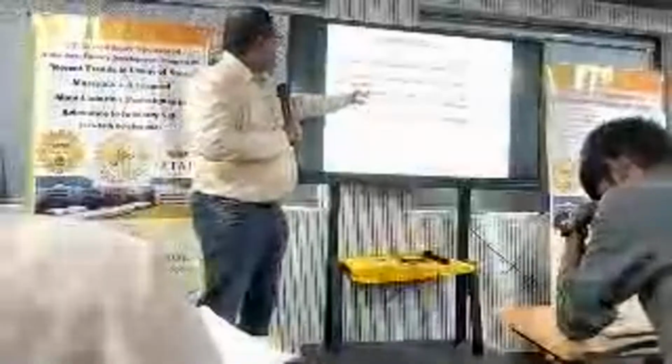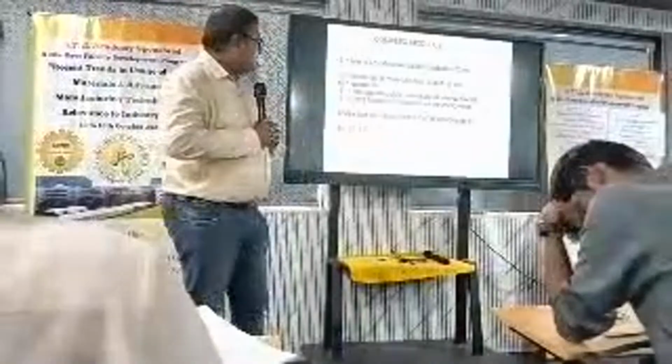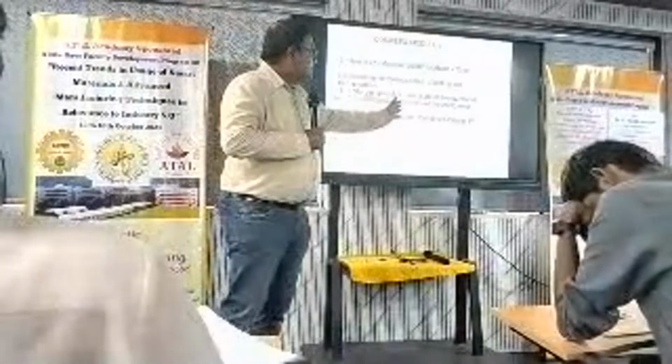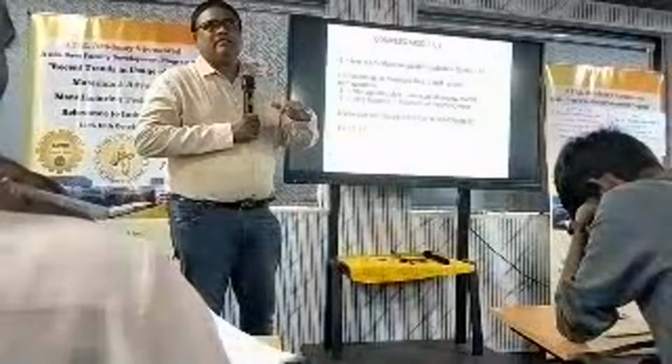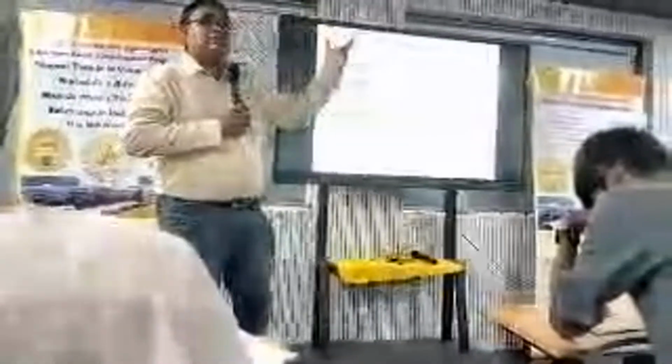E star is a complex number which mainly depends upon the storage modulus and the loss modulus. Loss modulus is the measure of energy lost, meaning how much vibrational energy is dissipated. That primarily depends upon the loss modulus. The higher the loss modulus, the better for us, because that much vibration energy is lost.